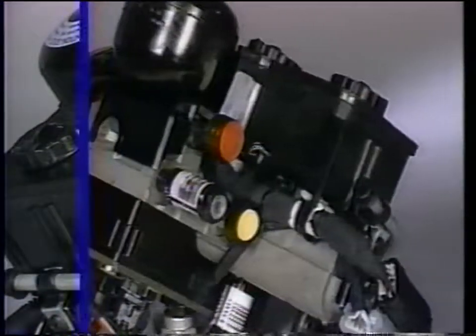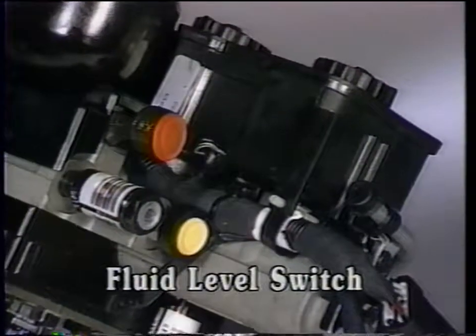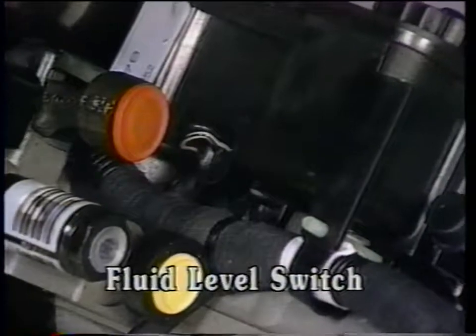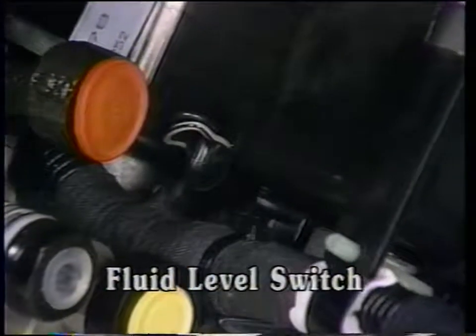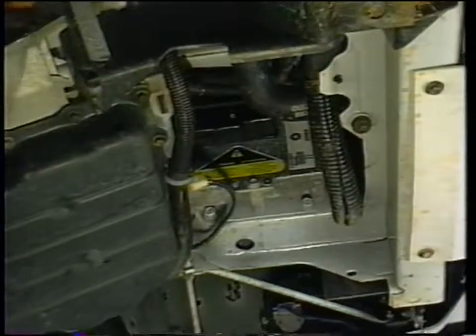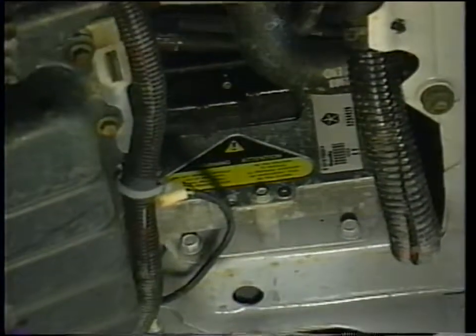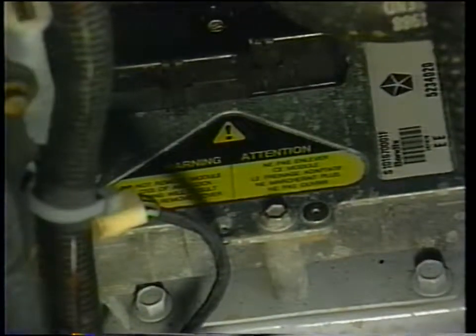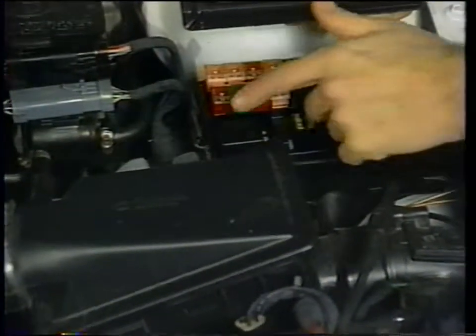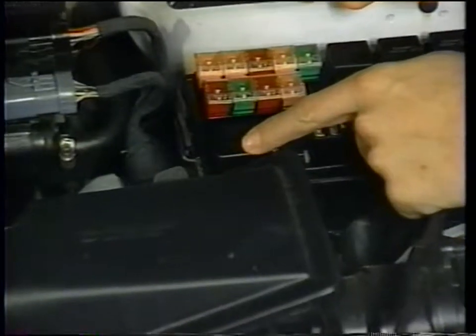A fluid level switch on the reservoir keeps an eye on the fluid level. The switch consists of a float and magnetic reed switch which closes when the fluid level is too low. This will illuminate both warning lights and disable the ABS system. The controller in vehicles with the Bendix 10 system is usually found under the battery tray. Power to the controller is provided through a relay in the power distribution center located on the left side of the engine compartment.